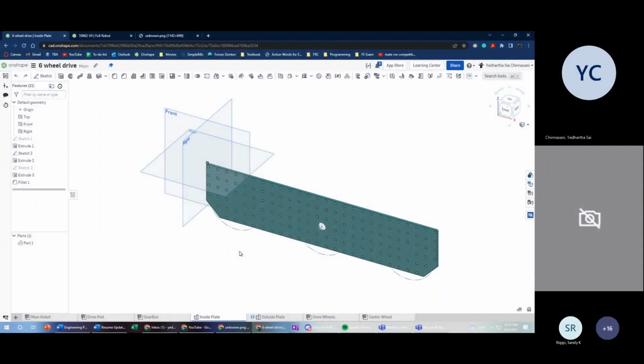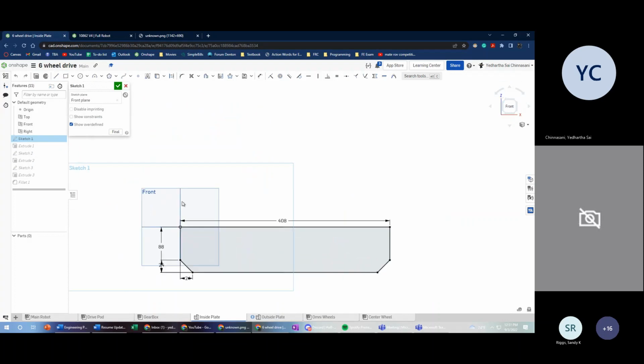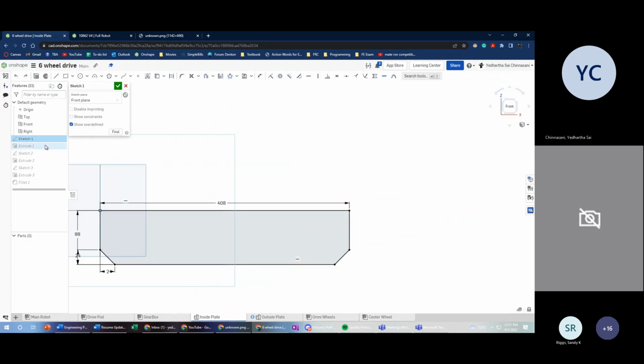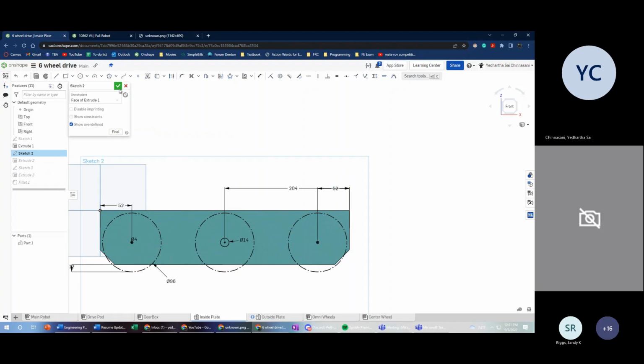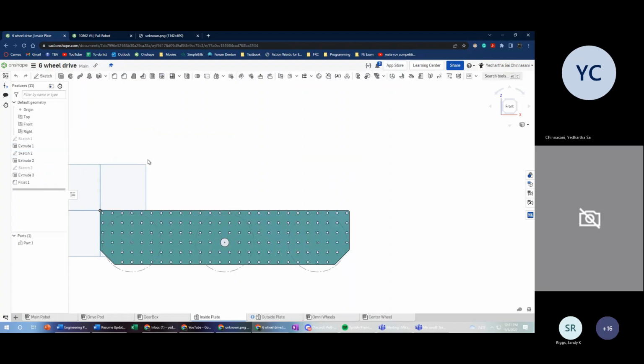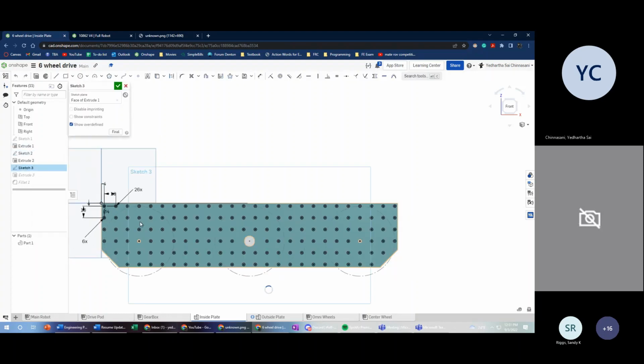So the one thing that I wanted to add that Sai went over that I think is really important is dimensioning lines and sketches. So he mentioned that if you have a sketch and everything isn't black, so if you have any blue lines, that's bad. And it's not just bad from the perspective of someone looking at your sketch. It's also really bad because if you look at a complicated sketch, and most of what you'll do for FTC is a decently complicated sketch, like what he's showing.